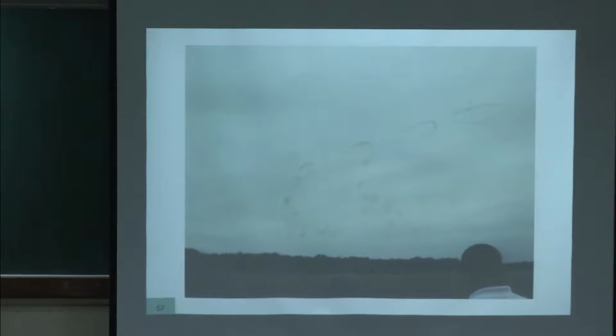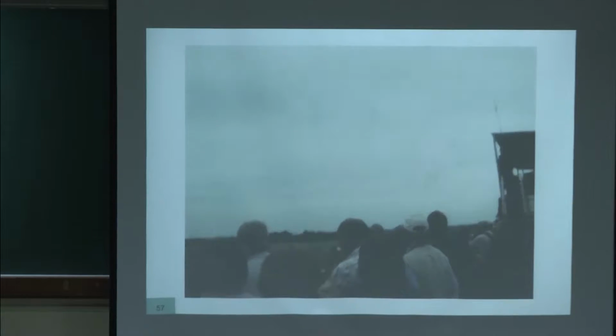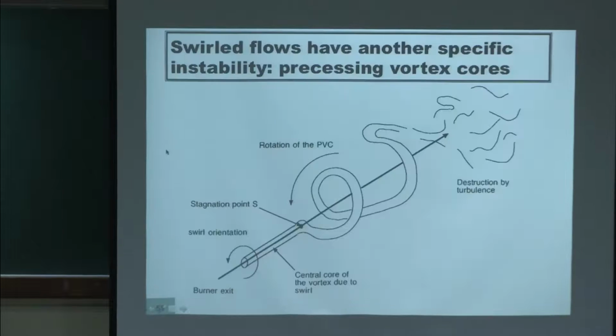So it really tells you that from a fluid mechanics point of view, every time you use a swirl jet, you have to expect, I would say, funny unstable modes. And this will be the case in combustion.